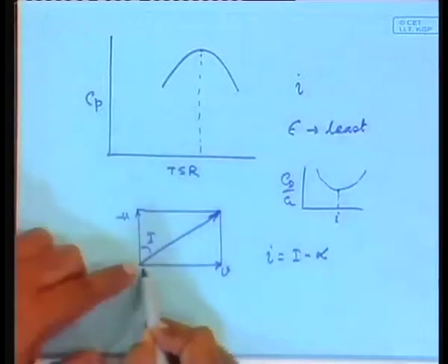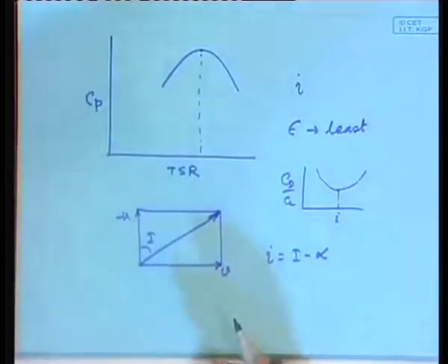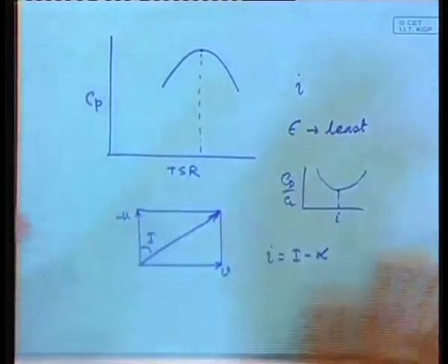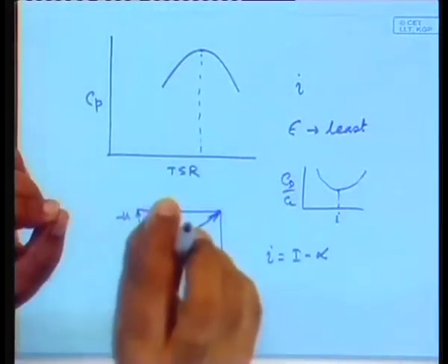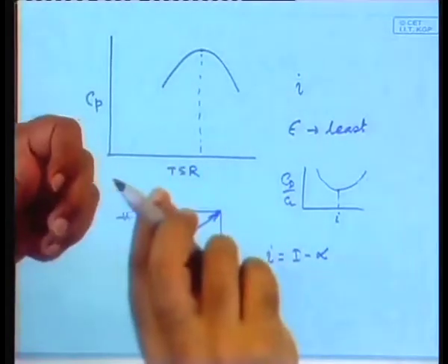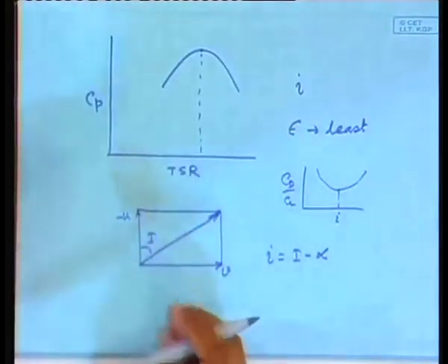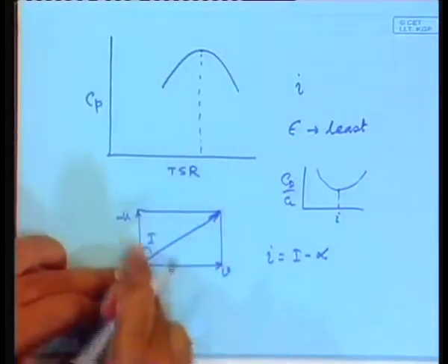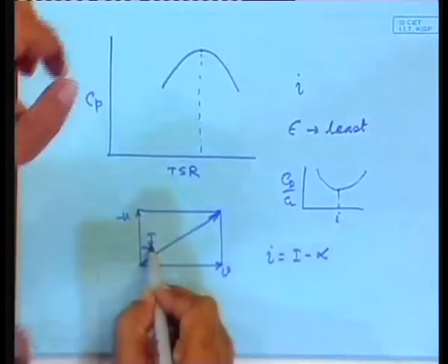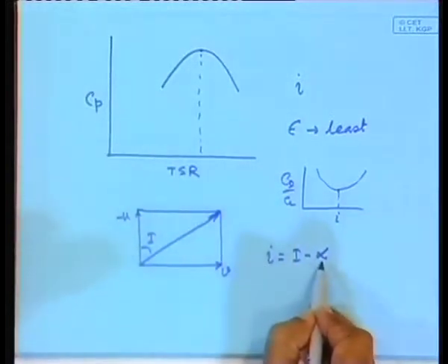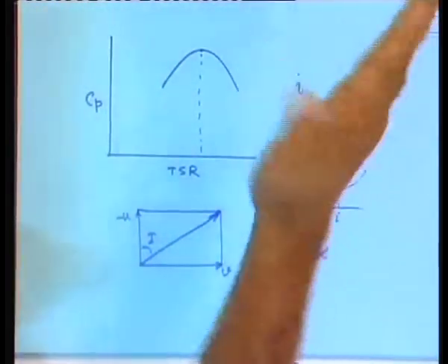Two reasons. First, V varies as the wind speed varies, and secondly U varies. At this point of time, we are not considering the variation from the inside edge to the tip. We have already seen that it varies, and for that we need to give a twist. But here we are considering the speed of rotation of the whole thing, and as the V changes, I changes, capital I also changes, but all the time your objective should be to keep small i constant, and that can be done by continuously varying the alpha pitch angle. So, the pitch angle has to be varied, right.